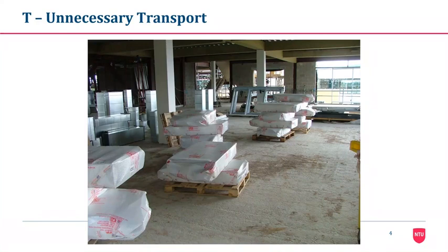The consequence of this was that they needed to be moved in bulk up the building as apartments were completed from the ground up. This was a lot of extra transport of materials, and many were damaged during the continuing movement and storage. The problem was resolved by arranging for smaller batches to be delivered just in time, so the materials could be taken straight to the place of installation. This removed the need for double handling and reduced the instances of damage.